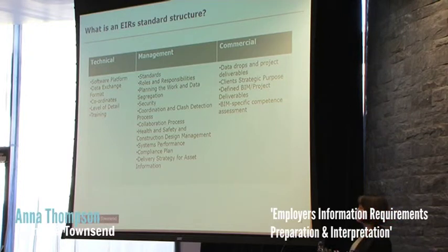If I look at it from a cost management perspective, so my background is I'm a chartered quantity surveyor, so don't hold that against me. But at the beginning of a process, when we receive drawings or we receive a model, and we're creating an estimate, if I use a door as a simple analogy, our cost managers need to know it's a door and how many of those single doors there are. But as the design develops, we need more information. So we move into cost planning and bills of quantities. So what we're saying to the designers is, you know what, we don't expect to see everything in the model at the beginning of the process. But we do expect, as the model develops, to have more data attached to those objects.